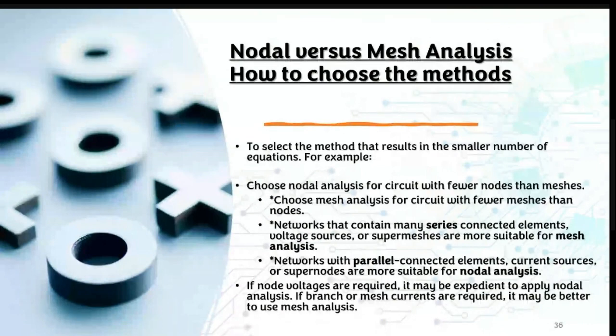So between nodal versus mesh analysis, how do you choose your method? This is when you have a circuit and it doesn't mention what analysis you need to use, whether mesh or nodal analysis. You select the method that results in the smaller number of equations, because with fewer equations it's easier for you to solve the circuit.